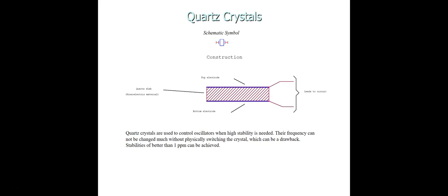Now here the quartz, among other natural materials, exhibits what is known as piezoelectricity, or we can say pressure electricity, which means when a force is applied to the quartz crystal, it bends very slightly. When the crystal bends, the internal atomic structure is displaced. As a result, a small voltage is developed across the device. Increasing the force will also increase the voltage. So basically it is converting a non-electrical quantity into an electrical quantity. Here force or pressure is our non-electrical quantity, and it is converted into the electrical quantity.